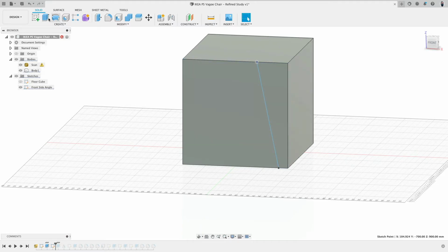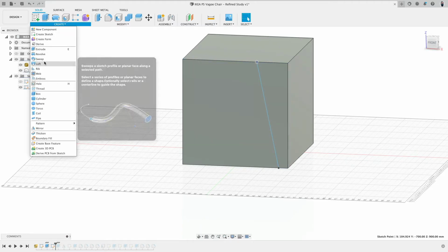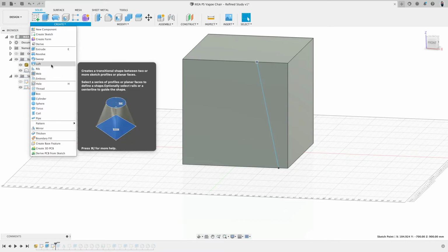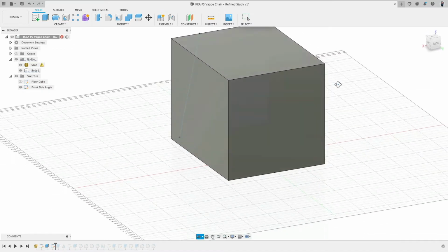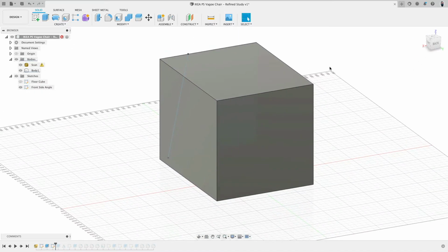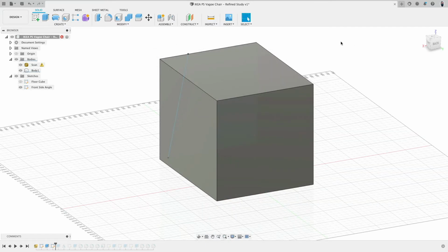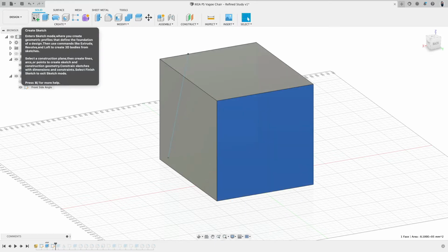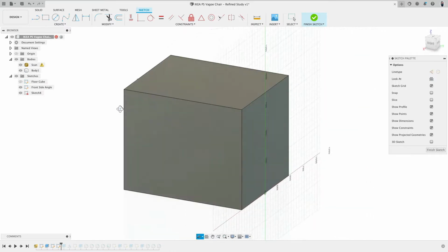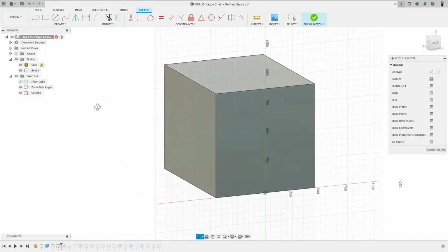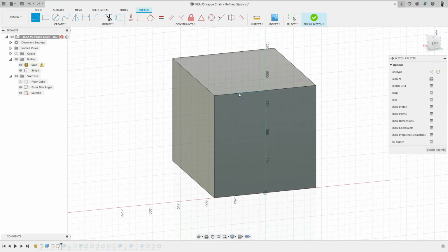Pretty easy. Instead of using the extrude, we will use the loft. For the loft, we need two profiles or sketches. Let's look at the back and create sketch on this face. What's also very easy to make sure the sketch goes to where we want it to, we select the face and then go create sketch. And you see, it's there. Then line command, click and click.